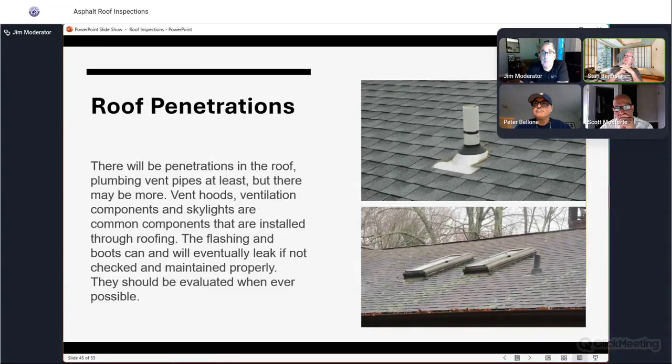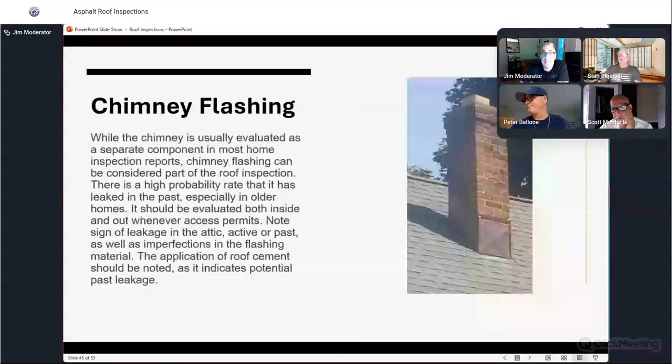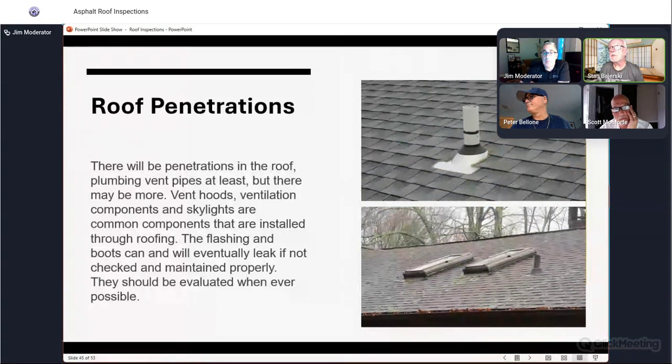You've got to look hard at that stuff. I may be off base a little bit, but I don't think a skylight lasts much more than 20, 25 years. If you're changing your roof, you should be changing the skylight as well. Absolutely. Even if the glass is going to fail, you can't replace the glass section. You got to replace the whole skylight.